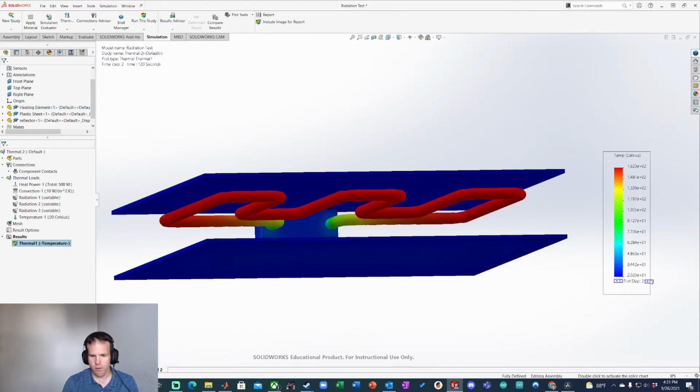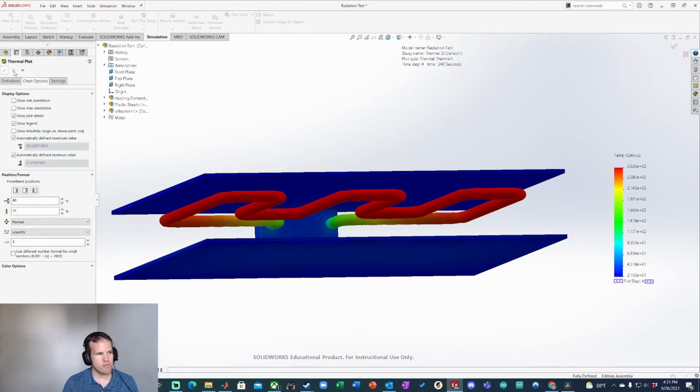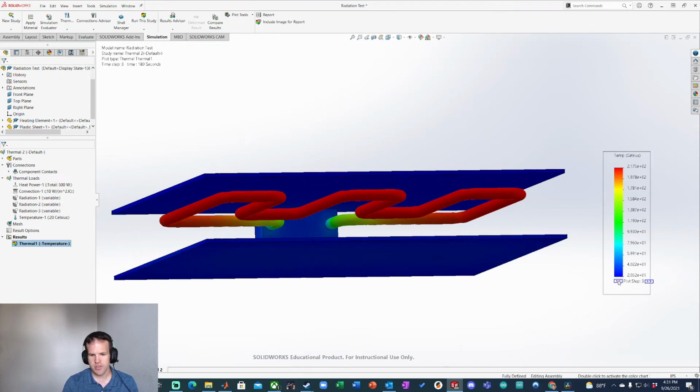I can click forward in time right here. So we see the colors starting to change as I click forward in time. And we can see the max value has also been changing while I've been clicking. Another tip is you can actually go backward in time. Oop, don't double click on that. Just steady single clicks. Now from time step 1, I can go back to time step 10 in reverse. So I can jump between time step 1 and time step 10.